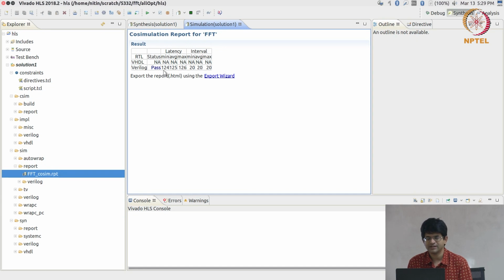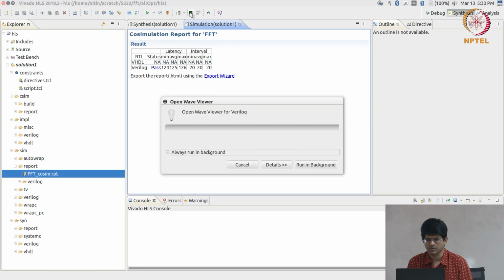Okay? Why these differences? Because the co-simulation is actually implementing the memory block and so on, and measuring the difference between start and done signals. Whereas the other one is just estimating based on the delays of each individual module and adding it up. There could be errors in how it is estimating it. Usually not much, so you don't need to worry about that typically.